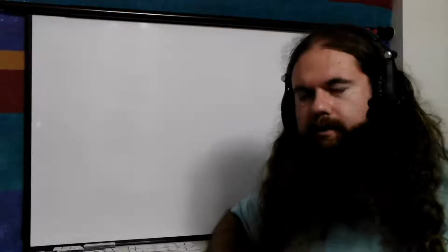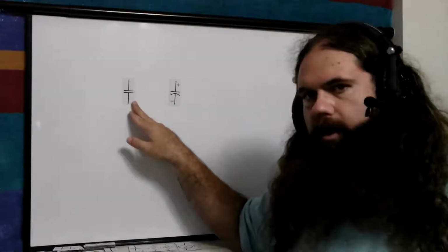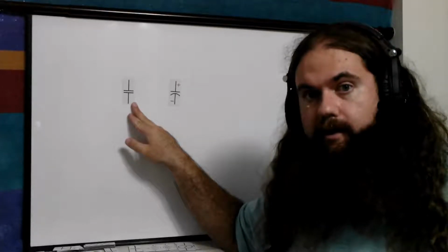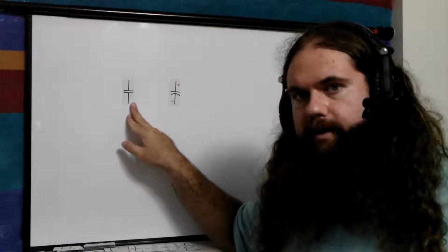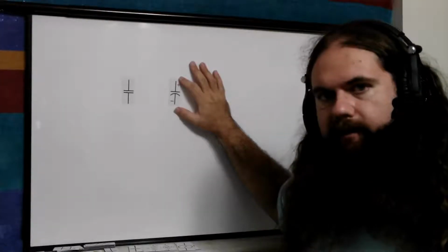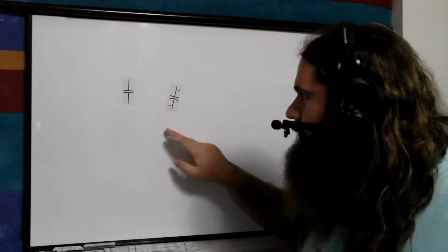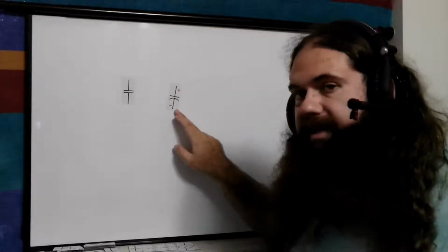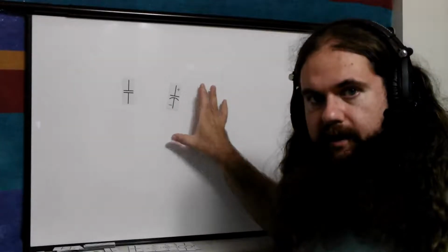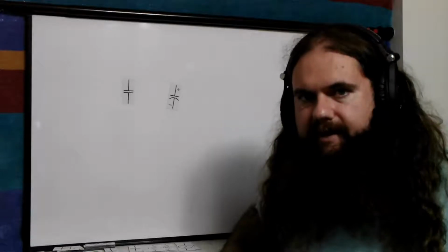Capacitors are two-terminal devices. They come in two types, nonpolar and polar. Nonpolar capacitors can be charged and discharged in either direction. They're very open-minded that way. Polar capacitors, you always want to have positive here and negative here. When you charge them, you put positive charge in here, you put negative charge in here. When they discharge, the positive goes out here and the negative goes out there. If you hook them up in reverse, bad things happen.